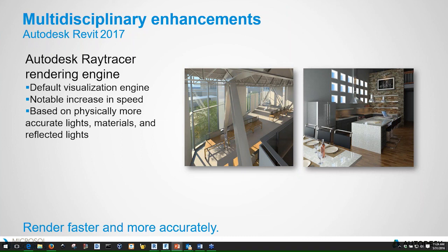What the trade-off might be, and this is pure speculation, is that Mental Ray or the Mental Ray algorithms might have taken some artistic licenses or freedoms to enhance your rendering, and Ray Tracer will probably give you the space the way it is right now. So if you want a much nicer rendering, you probably have to pay a lot more attention to how you set up your lights, how you set up your materials, and so on. But to the naked eye, to someone who doesn't do rendering for a living, you probably won't be able to notice the difference.